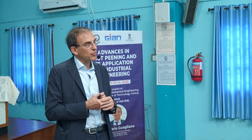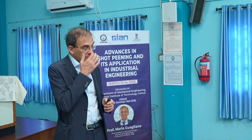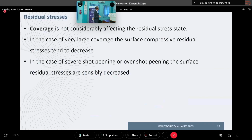We are going to relax what's happening in the surface due to the fact that some surface damage is going to happen. And this is even more mitigated in the case of severe shot peening, where the surface residual stresses are going to decrease, but at the same time remain valid for improving the mechanical strength.